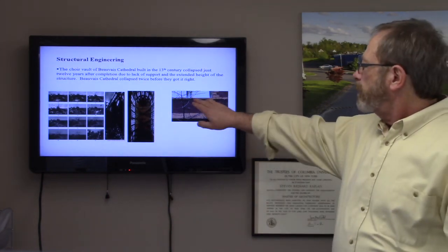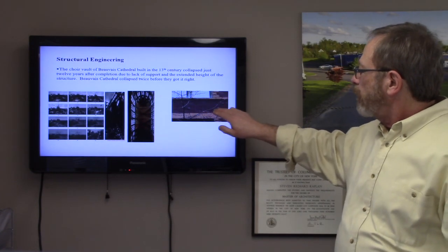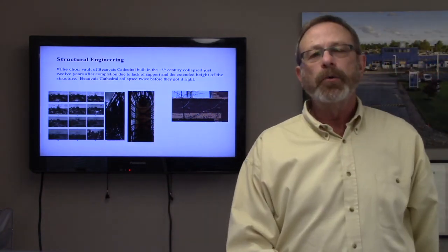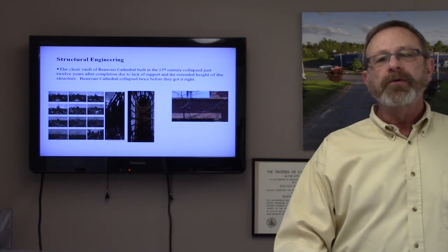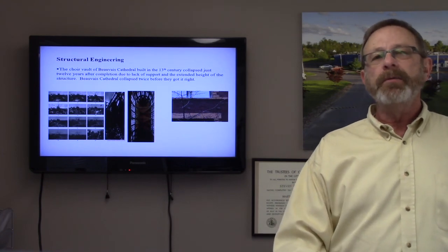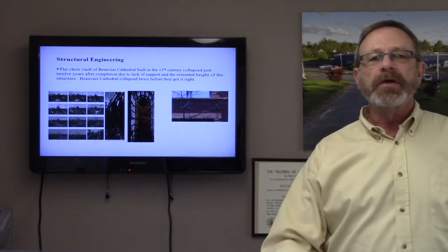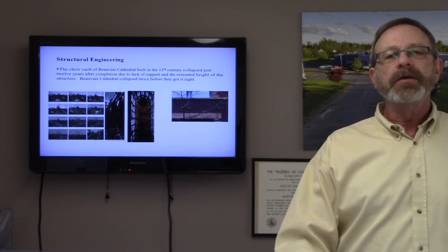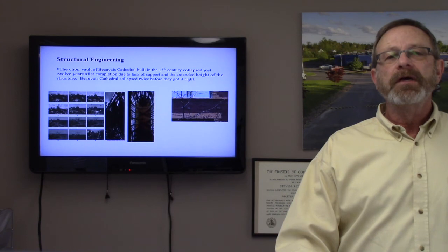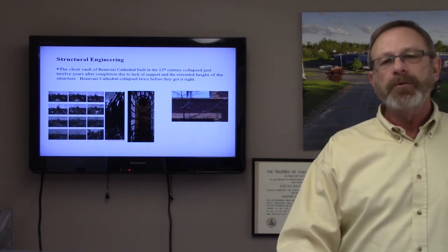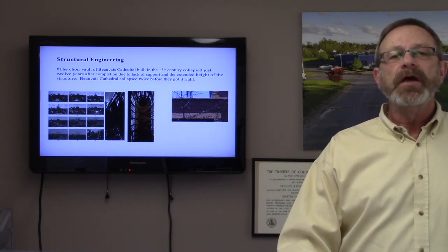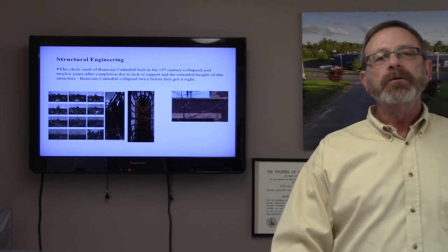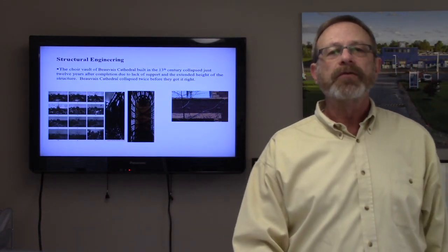We can see here in this brick sample the outline of brick failing at the mortar joints. Before it does fail, however, the material may develop a permanent deflection, such as what I just pointed out. It then begins to behave in a manner that is no longer elastic. The appearance of permanent deflection, such as a crack shown in this picture on the right, often provides advance notice that a structural material is in danger of collapse.